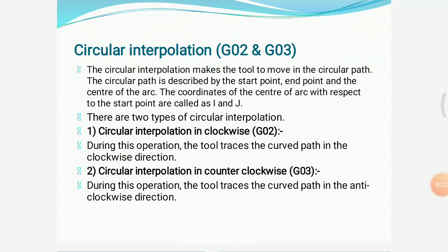Dear students, in this video we are going to discuss circular interpolation G02 and G03. G02 code is used for circular interpolation in clockwise direction and G03 code is used for circular interpolation in anti-clockwise direction. The circular interpolation makes the tool move in a circular path.